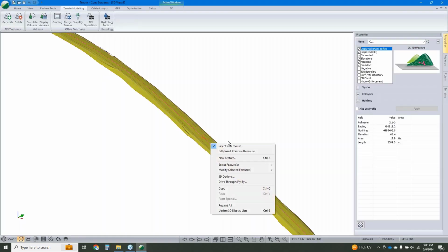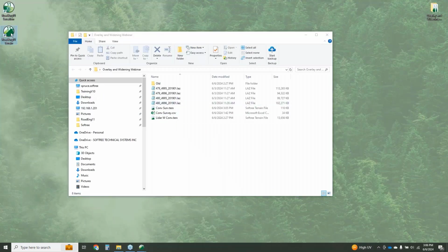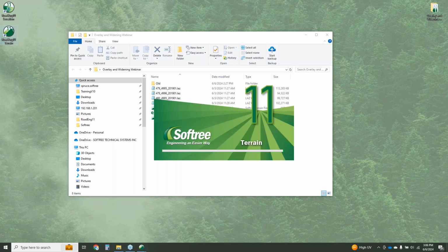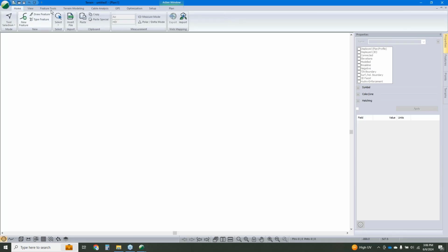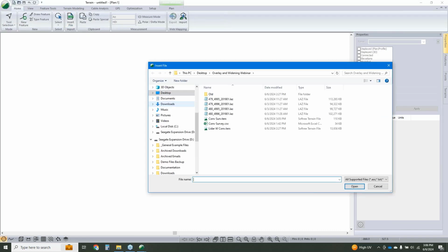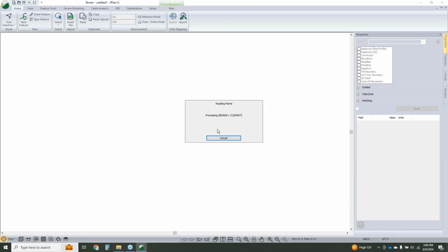And just to have it, I'm going to use that center line. So this is one of the things that there's kind of two ways to do it. If you're combining your LiDAR data and conventional survey data, you can just insert the two into the same file, or you can do a merge. So the merge is we're going to take out all the survey data in the LiDAR data set that overlaps with our conventional survey data set. This will make a bit more sense once we bring it in and actually do it.